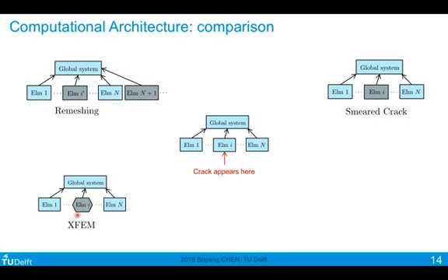So before any crack, this element I is a standard finite element, which uses the standard shape functions for interpolation. After the crack appears, this element I changes and includes all these additional interpolation functions, such as Heaviside enrichment and crack tip enrichment, so that the solution field changes to better represent the actual displacement field near the crack.